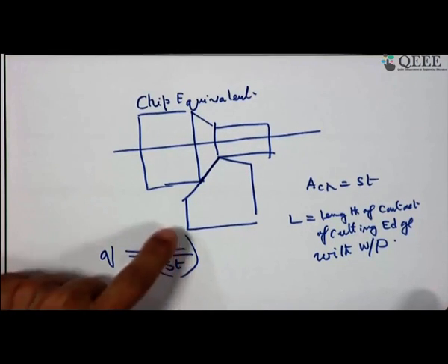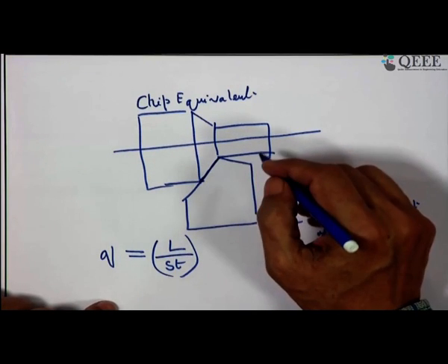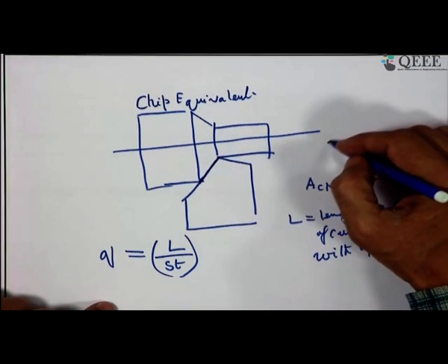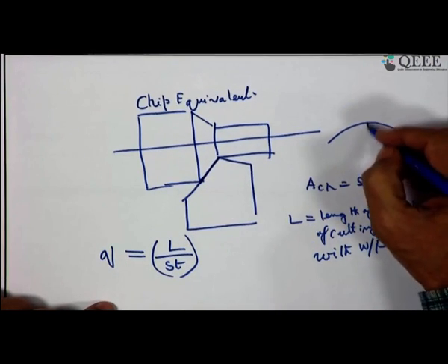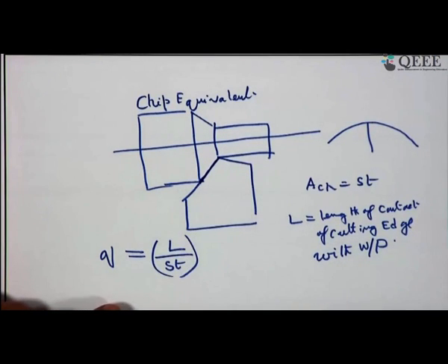If we increase S, similarly, proportionally the value of L should be increased, either by depth of cut or by radiusing. If we have radiusing, we get a larger contact. So, holding the chip equivalent constant, we can also keep the cutting temperature constant.